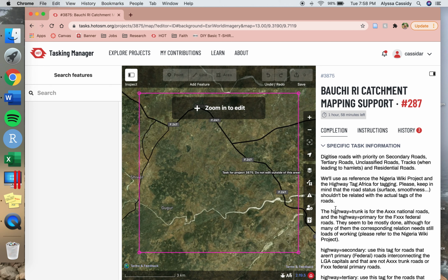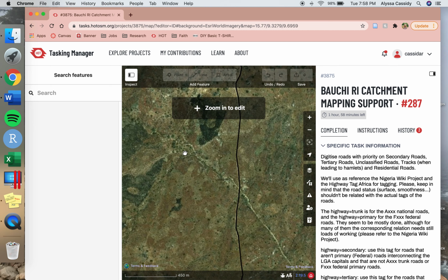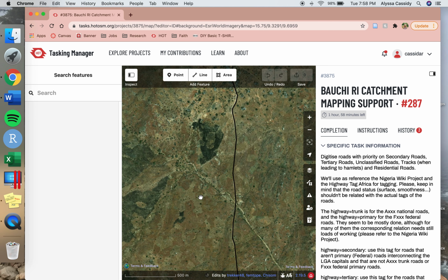resume mapping. So the first thing we're going to do is look around for waterways. We can see that there's a big river right here. The thing to look for when looking for waterways is a lot of bending. So they probably wouldn't have constructed a road to be this wiggly. We're going to go in here because I can see some over here. Another thing to look for is that waterways are at the bottom of valleys. So you can see that the land kind of slopes in here, and we see this waterway.